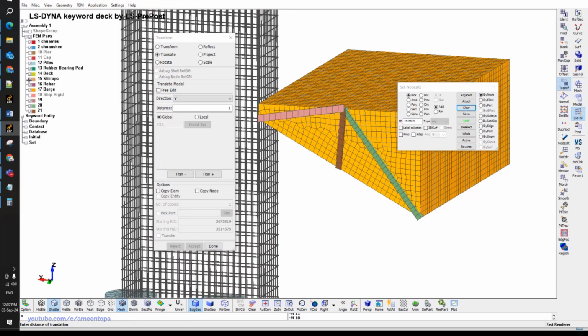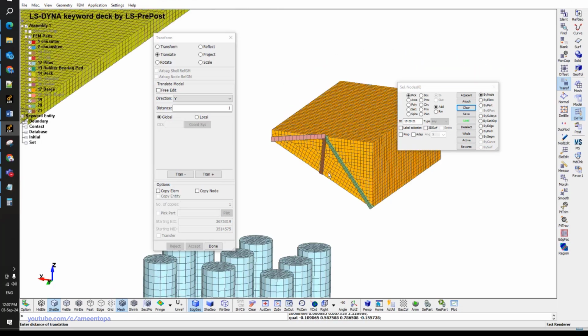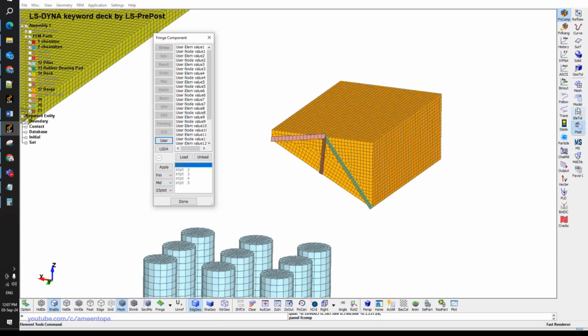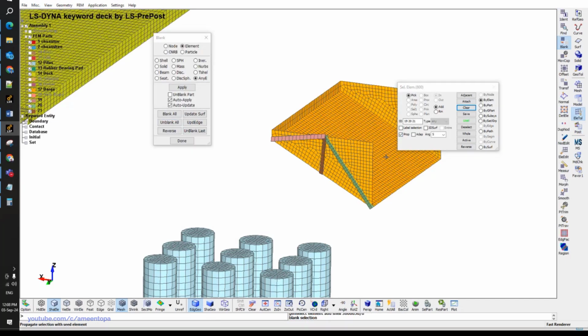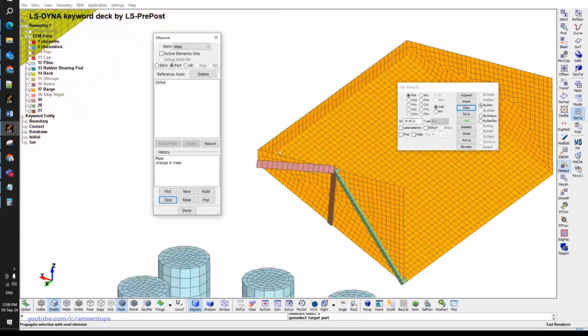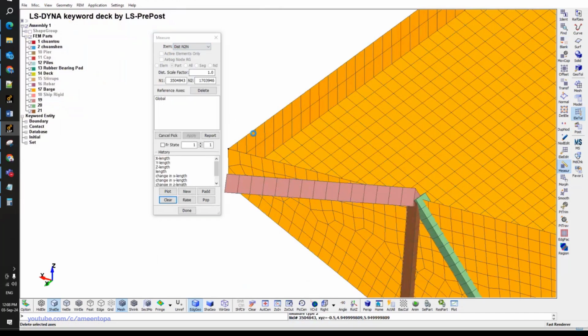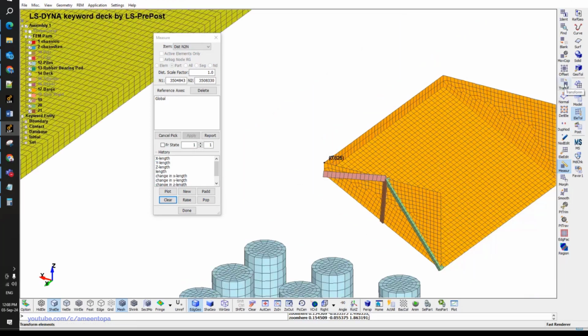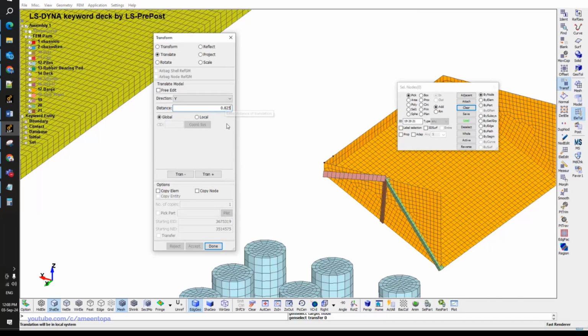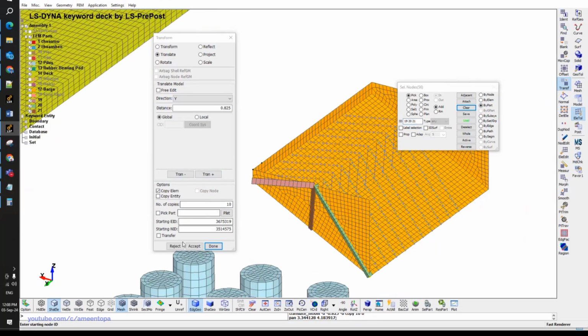Tab, we hide this all. Click on F8. F8 and hide this and this. So here we have, oh, sorry, F4, measure the distance, 825. So we will stick with this value. And then maybe make it 10. Select by part, select the nodes, select the parts. Still not enough. We make 20 and then we delete the extra.